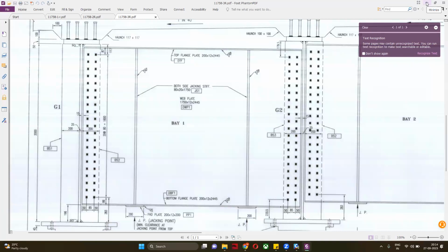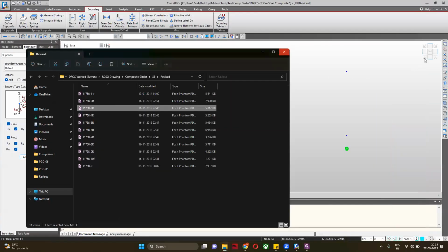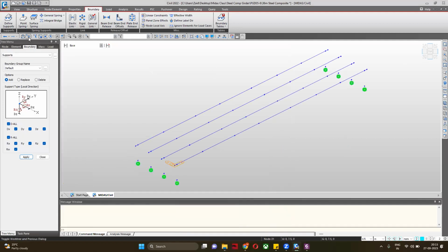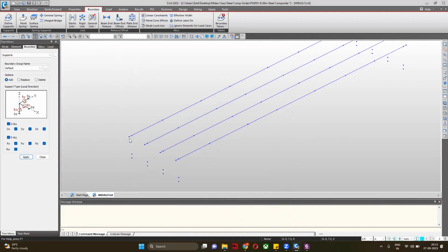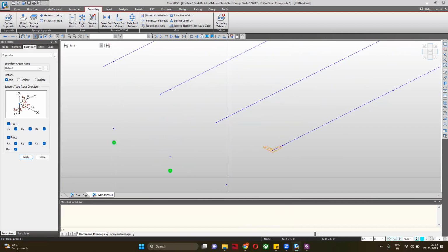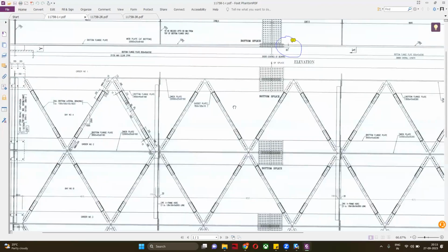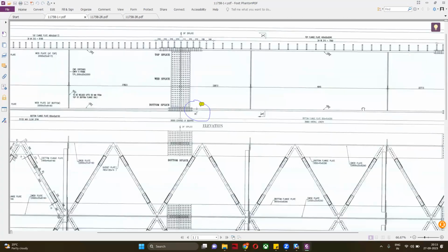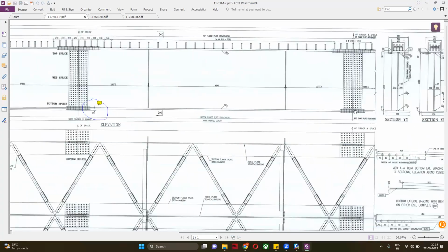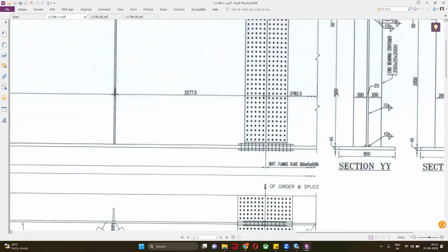Here is how we generally do it in steel, let me show it. First I need to create for the end diaphragm, nothing else. I know the distance between them, now I need to provide it at this location, in between this 2 meter. From the bottom, how much will it be? 45 plus half of this, so around 1.45, or if you want, 1.045.